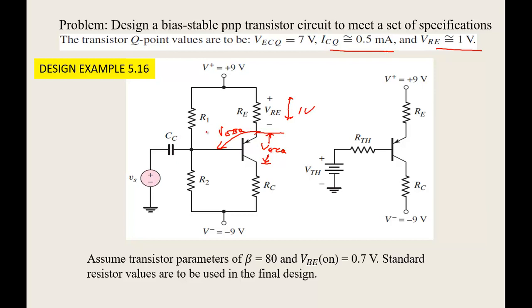And the best part is there are no values of resistors given to you. You have a dual supply, plus 9 volts and minus 9 volts. The first thing you can do when you see a circuit like this for a DC analysis, and this is DC analysis only, we are not doing any AC analysis here, is open circuit the capacitors. All these things will be removed, so we are left with only this circuit, R1, R2.